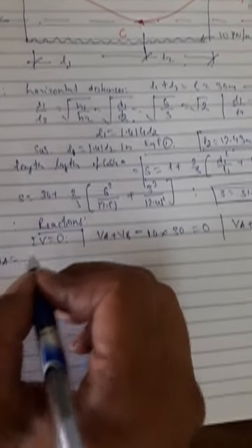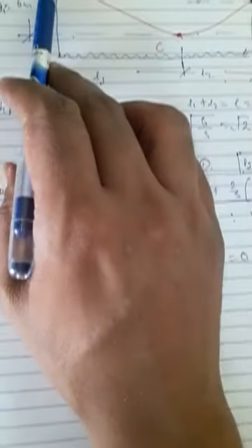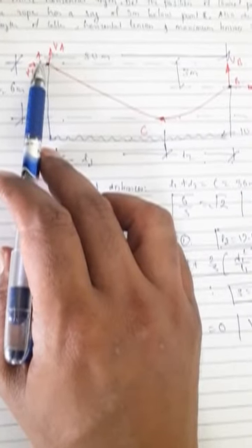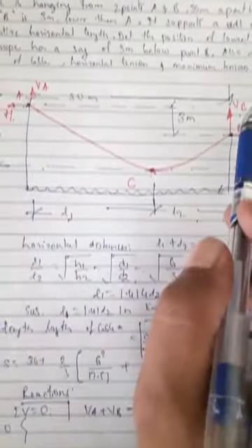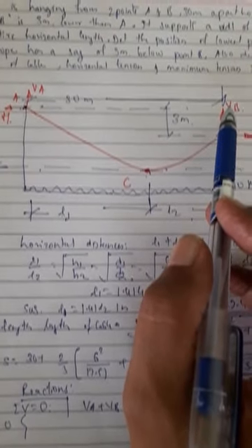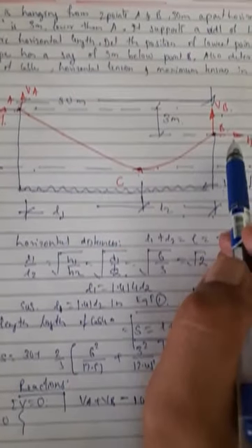Now let us start writing about hinge points. Summation of moments about A is equal to 0. Clockwise forces are positive. Keep your finger at A, start analyzing the beam. So when I start analyzing from A, I can write VB into perpendicular distance 30. So VB is negative because anti-clockwise, minus VB into 30.